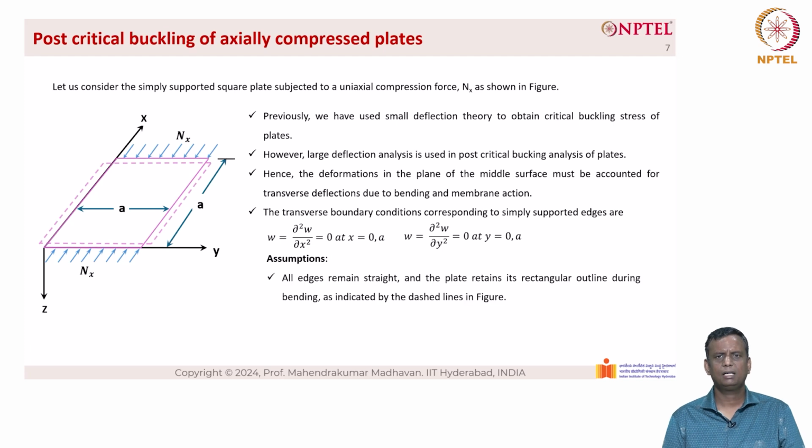The assumptions are that all edges remain straight and the plate retains its rectangular outline during bending, as indicated by the dashed lines in the figure. On the left hand side, you see the dashed or dotted lines. Here, they remain straight. The shear forces Nxy vanish along the four edges of the plate, and the edges y equal to 0, a are free to move in the y direction.